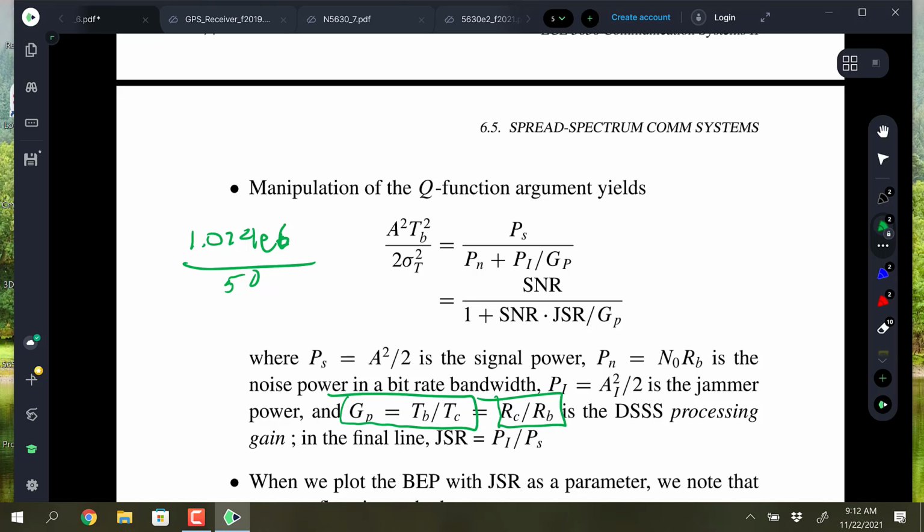So now what type of jammers makes spread spectrum more vulnerable? CW is good because it spreads them out, but you can have barrage jamming, wideband jamming. There's a whole suite of jamming types that systems get tested against, and so the CW is the easiest one to analyze. We're not looking at the other types, but barrage jamming is where the enemy is just sending broadband noise at you, but it does it in a pulsed fashion usually because they have to conserve energy. They can't just keep that high power up. But there's all different types of scenarios that people can use for jamming and jamming effectiveness.